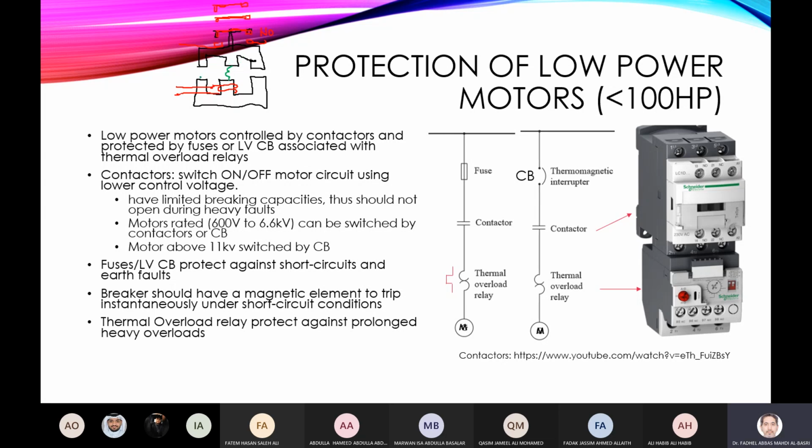When you energize, this will be pulled down, and these contacts will be closed and the current can flow. For three-phase, I have three main contacts: phase A, phase B and phase C. I also have additional auxiliary contacts, some of which are normally closed, and when you energize, they become open. This is the basic construction principle of most contactors.